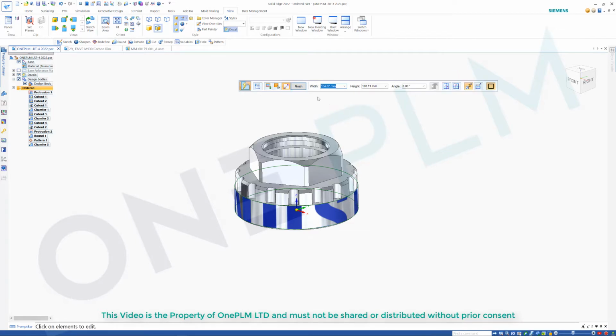If I click on that, it will give us the size, the angle, and mirror options, and options to unlock the aspect ratio and reset the aspect ratio, and to turn off the border if we've got a border. And then if we click that again, that will take us back to our offsets. Our offset values are actually meters, so something point something meters. But for this one, we're going to go to our decal display step.